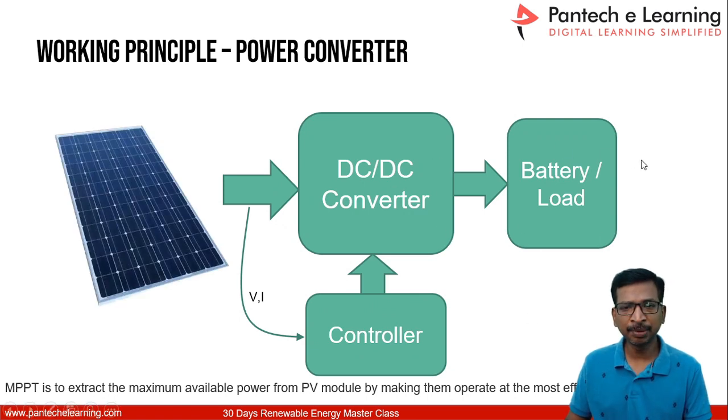For example, in this block diagram, the load may be either a battery or a resistive load, whatever it is. Here, due to the sunlight variations, the power generated by the panel will vary from 0 to maximum, at the rated power. So now we have to implement one DC to DC boost converter along with the controller. This controller is going to monitor the panel voltage and current. From this it will derive the maximum power. Based on this power, this controller is going to work.